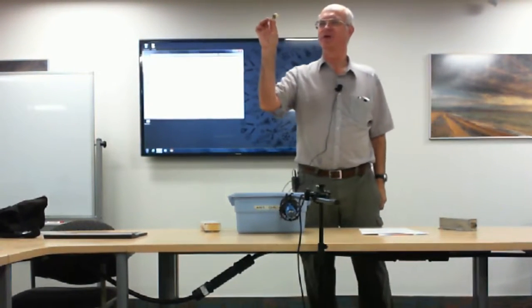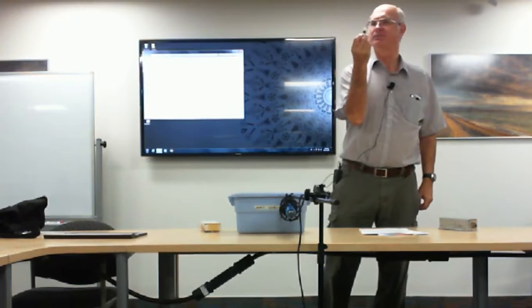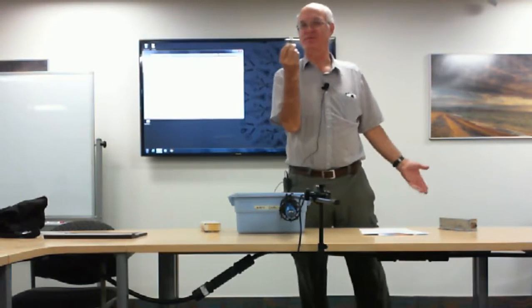Telephone interference. Same thing again. It comes in on the phone wire. Well, there are filters for that. This happens to be a commercial one. You just plug in one side, plug in the other side, close to your telephone, a short piece of cable. It prevents the frequencies from getting in to get messed up inside your phone. It takes them off the line. This particular one is made of a capacitor and a coil, so it's a tuned circuit, or a filter.